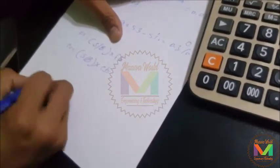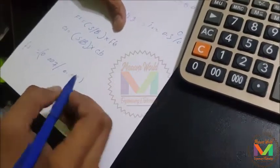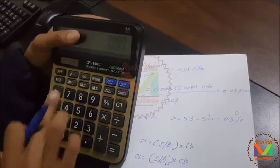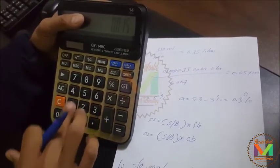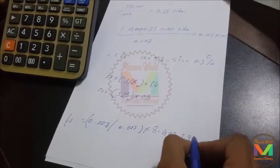we get the mass of fine aggregate, FA, equal to 0.007 divided by 0.015, and we carry on, multiplied with 8.40. I need to calculate it now. FA is equal to 0.007 divided by 0.015 multiplied with 8.40, which is equal to 3.91. We will round it to 3.9.